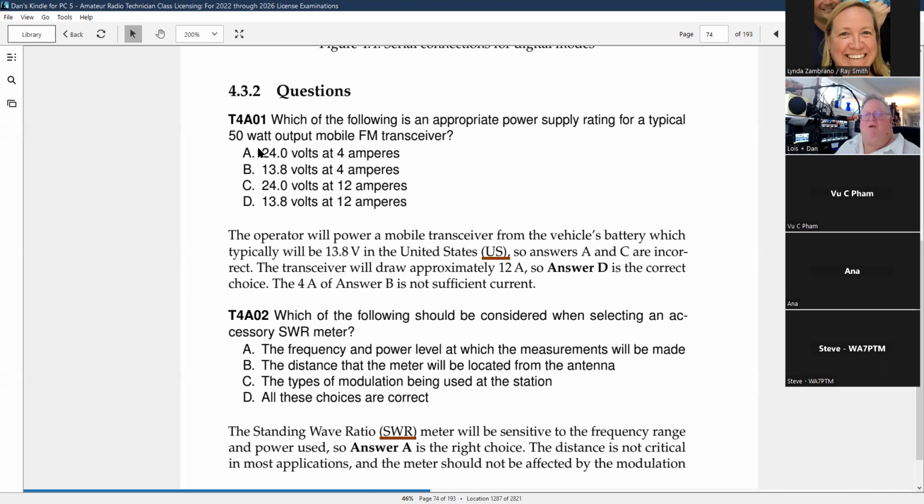This, though, is 50 watts of radiated power, of radio power going out, and a lot of power is lost in the device itself. In fact, my radio I showed had those ribs for cooling. If I transmit constantly, it gets really hot. So the reality is 50 watts of it goes out, but there's a lot of overhead, other processes, power loss in the radio. That's why your only choice is 12 amps.